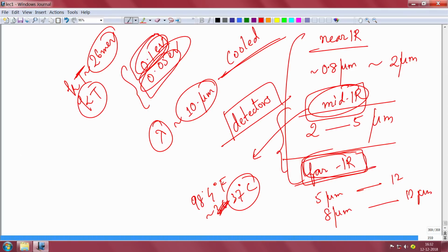Okay, so we shall end our lecture here today. Now we are done with photo detectors. We have finished the photo detectors discussion. The various categories of detectors I have briefly discussed, also the speed, about how fast you can operate a junction photo detector. There are two limiting factors. One is that there is an RC delay because of the capacitance charging. The other is the transit delay that electrons and holes have to take to reach each other at the other ends. So both of the delays matter in deciding how fast the detector can operate. If you want to operate at 1 gigahertz, for example, the delay has to be less than a nanosecond, right? So all these things are important in designing photo detectors.